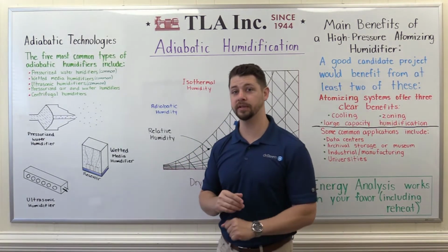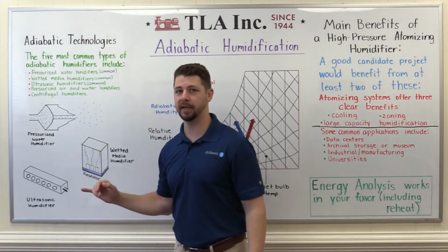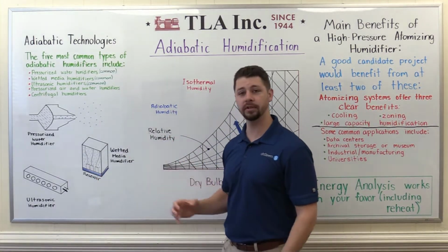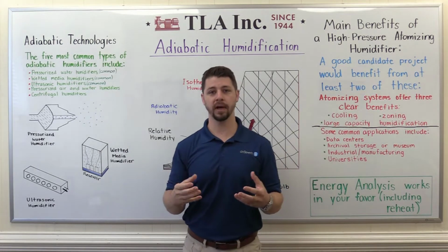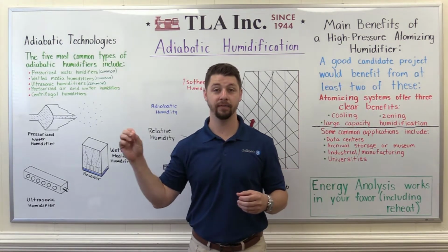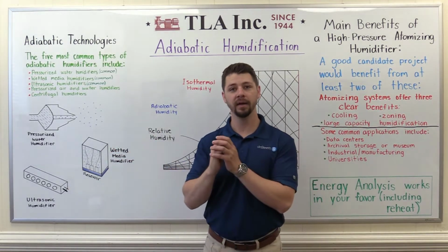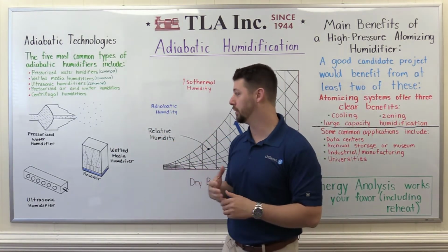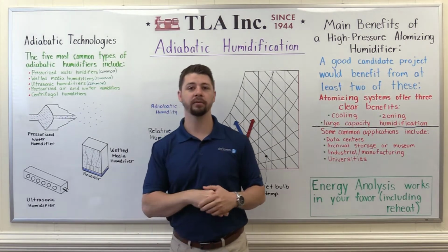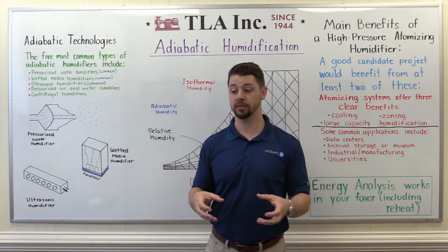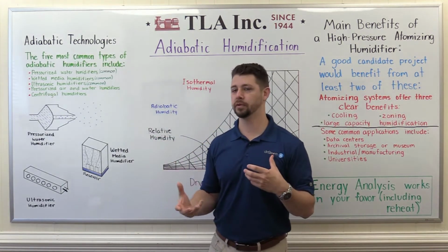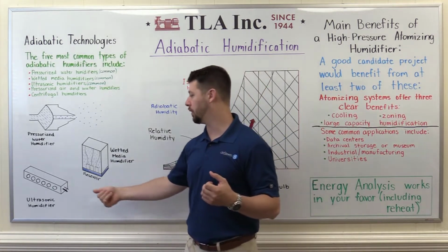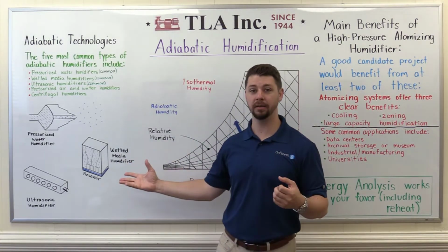There are several different ways to achieve this through a number of different technologies. You have high pressure atomization, where we're using pressurized water, RODI feed, at like 1200 psi. It evaporates into the airstream really quickly and we get that supplemental cooling. They have ultrasonic humidifiers, where you have these ultrasonic rotating discs, really good for small loads, but also requiring RODI feed. You have wetted media.